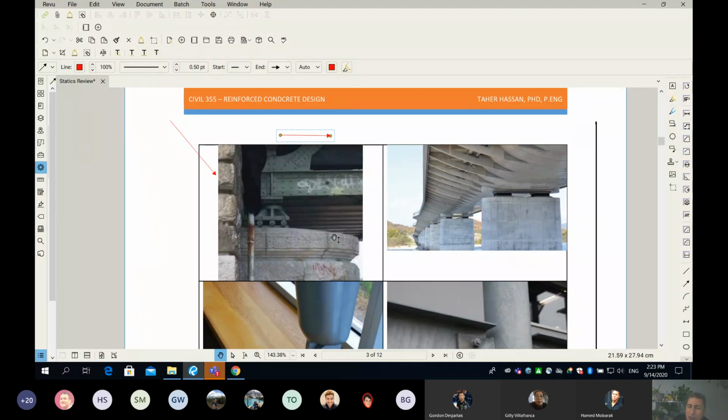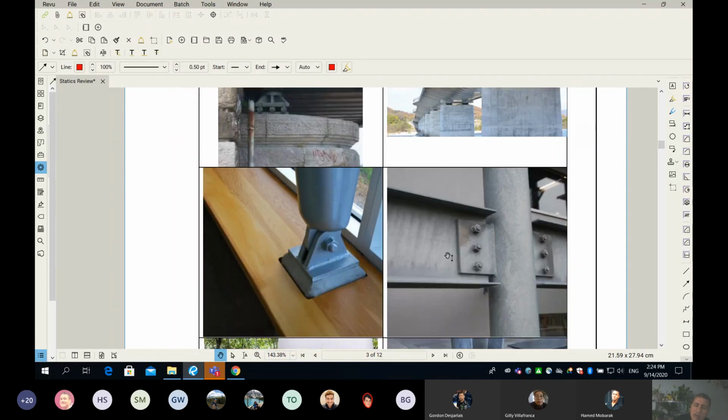And guys, why is this so handy and preferred? Because of the thermal effects, because of the temperature. This bridge is outside, and it will see a huge temperature difference between the morning and the night, between the summer and winter, which means the structure wants to expand or shrink. And if you restrain the movement in the X direction, you have a big problem. You just have to make it roller, and then you have to do something on the top for the joint. Okay, let's move on to another kind of support.